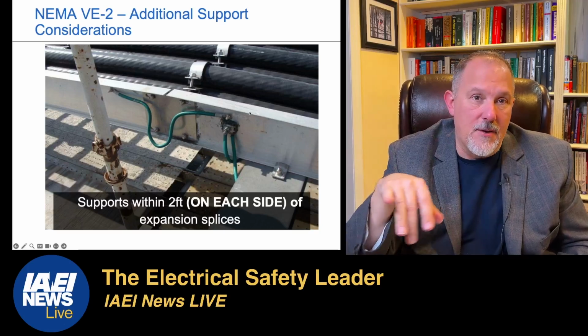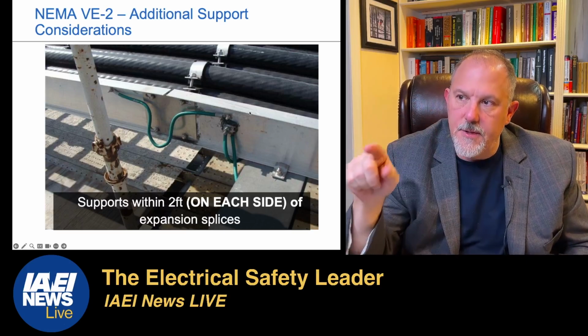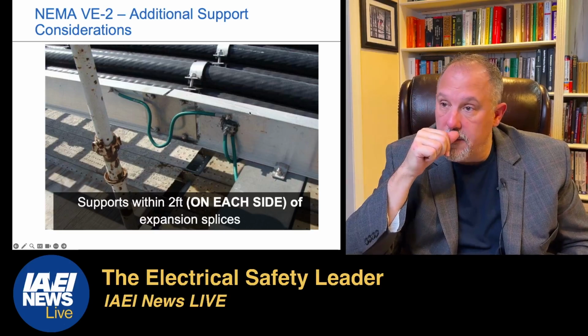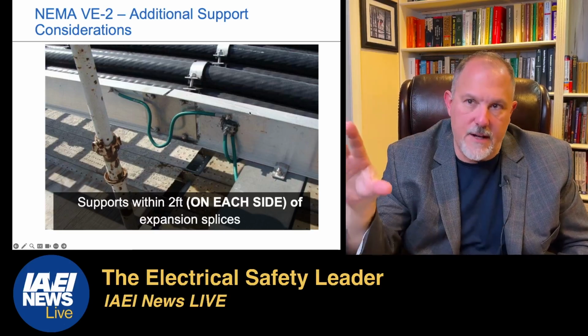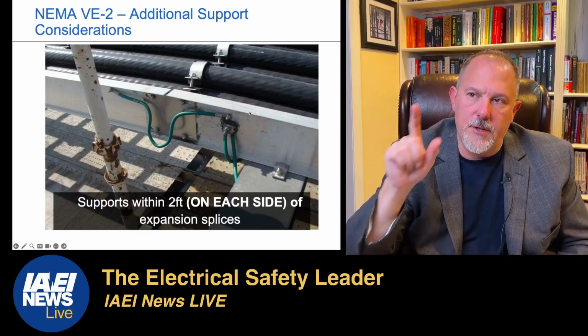And all the metal is all connected together, and for every one of those terminations, you have to think about the materials that you're terminating and make sure that you don't have dissimilar metals and galvanized, all kinds of stuff. So you've got to follow the manufacturer's instructions, make sure you buy the right parts and pieces.